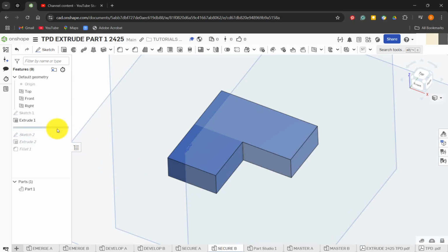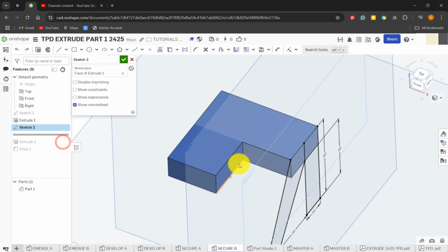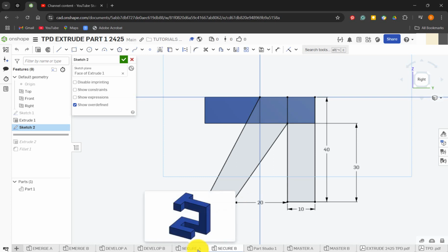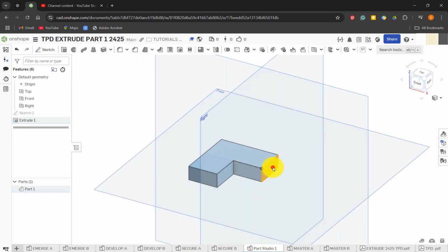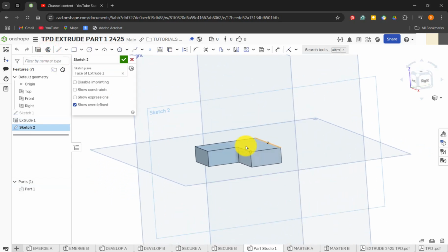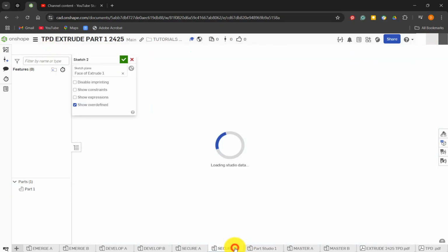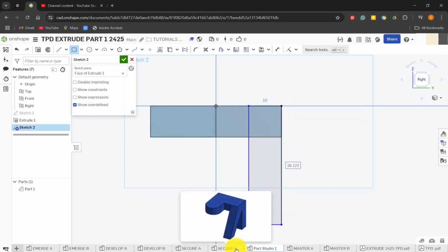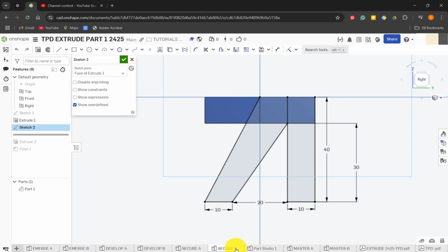So what I did next is I then created a sketch on this surface here. So if we have a quick look, flatten this, I'm going to do a little sketch of like this, roughly, and then I'll dimension it. So go on that side, press N, little sketch using the quarter rectangle to start with. And if we type in those sizes, actually, we're going to go for 40 by 10.